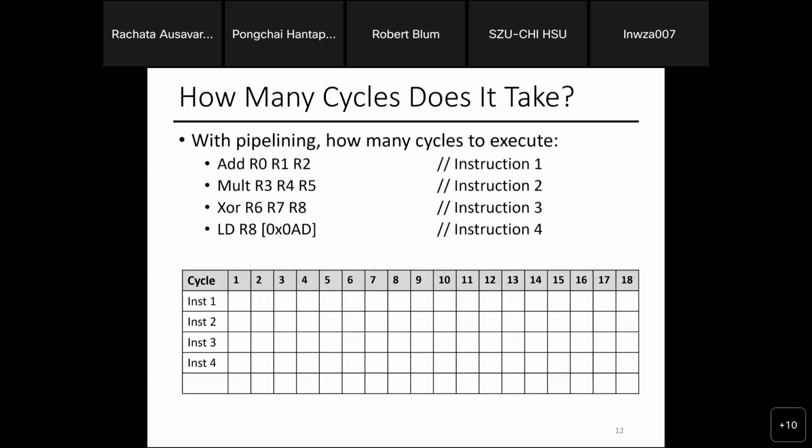Okay, so let's go over our earlier example, which is a bunch of these instructions, right? And let's assume a 5-stage pipeline. What we've seen earlier is called a 5-stage pipeline. If you have a deep pipeline, it becomes an N-stage pipeline. For example, many of your Intel, AMD, and Apple M1 chips have more than 30 stages. So you just call it a 30-something stage pipeline, depending on the design.